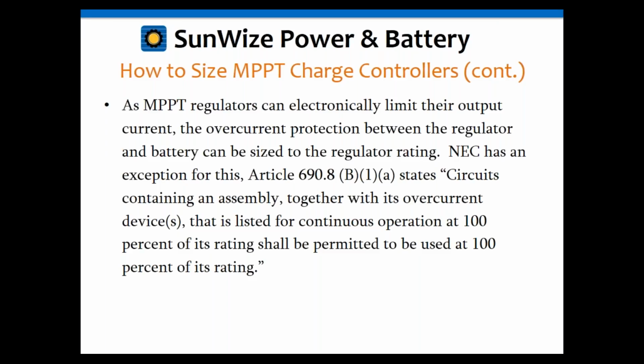That was actually put in mostly for the battery backup grid tie industry. Ones that might work with your Outback Power unit or your Schneider Electric stuff, they had this clause put in the NEC code that allowed them to use 60 amp breakers and 60 amp charge controllers for that.